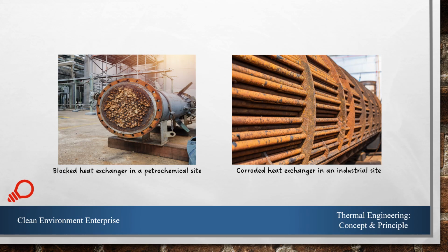So usually these are some of the operational problems that can arise during installation, and we have experienced many problems as well in the heat exchangers in power plants, especially the condensers, because we are using river water for cooling, and it is already contaminated or contains many other solid materials which block the tubes, and at the end you have to take these heat exchangers out of service.